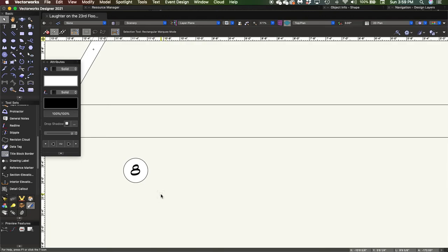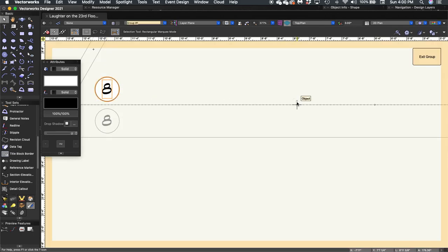I'm going to go ahead and turn this into a group so it just always gets moved together. So I'm going to draw a marquee around both of those and Command G to turn that into a group. And I'm going to grab that and move it up onto the stair. We need to do that once more because that's our 8-inch rise. We need to go to our 16, so I'm going to duplicate this. Command D. I'm going to move it straight upstage onto the next level, and double click on here to enter into my group edit section.